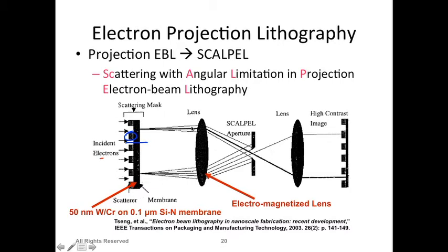When you have less scattering because of the aperture, you end up getting, you see, that's why the middle line is shown as more thick and dark, which shows that it's more intense. So it means more energy can pass through because of less scattering. But if there is more scattering, a lot of the electron beam would not be able to pass through this aperture. So only a little will pass through because of wider scattering, and you end up getting less electron on this surface where you may have a photoresist, right?